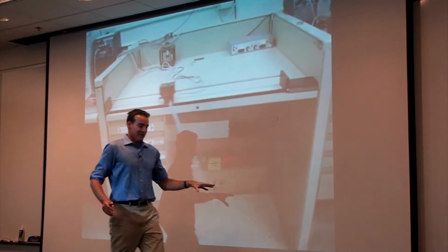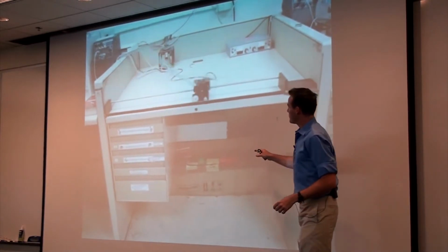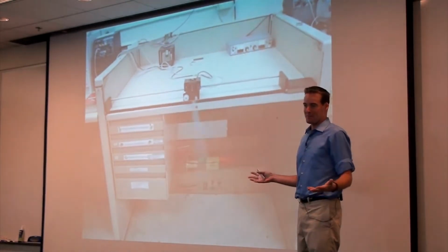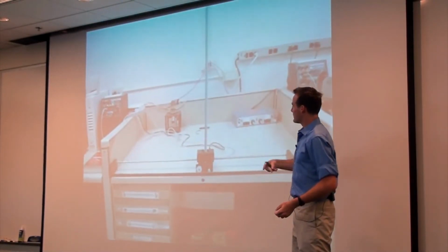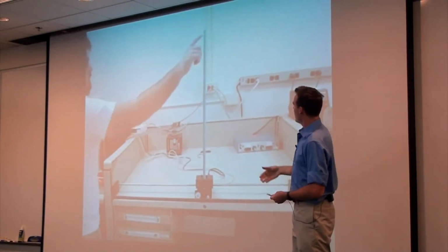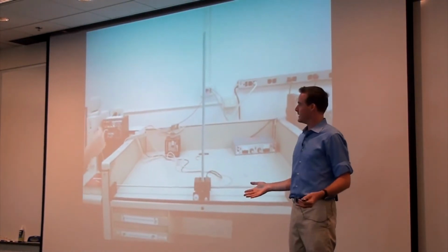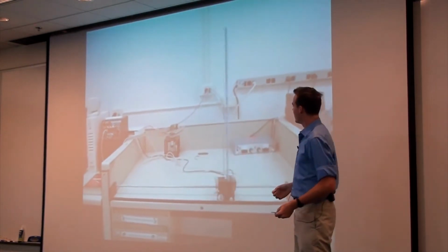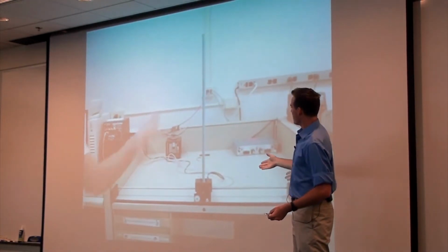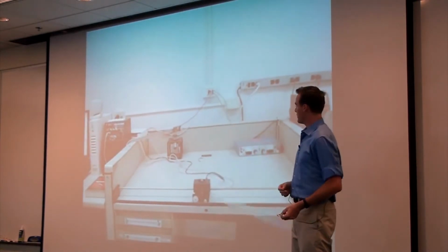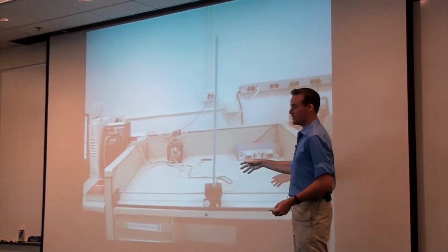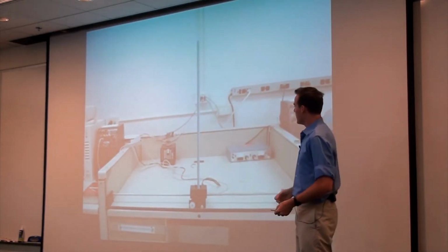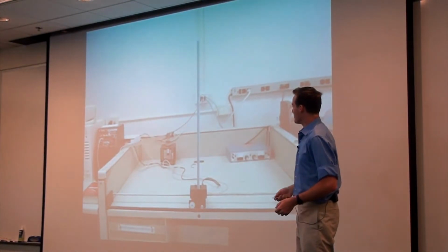So here's an inverted pendulum. The first control objective is to just invert the pendulum. So please just get it upright. It does this by pumping energy into the pendulum. And once it's stable, another controller kicks in, the goal of which is just to keep it stable, even though these kids are whacking it. And then it can switch back and forth between the 2 controllers. So if it loses it, it can still go back into the energy pumping mode and get it all stable.